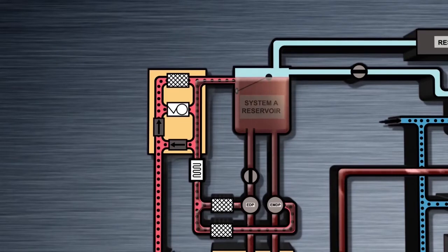Despite the cooling system in place for the electric pumps, there is still potential for overheating. Temperature switches downstream of the electric pumps in the case drain line monitor the hydraulic fluid for overheat. The amber overheat lights above each electric pump switch illuminate when these sensors detect an overheat condition. Note that there are no overheat lights for the engine-driven pumps. This is because overheat situations are much less of an issue for the engine-driven pumps.